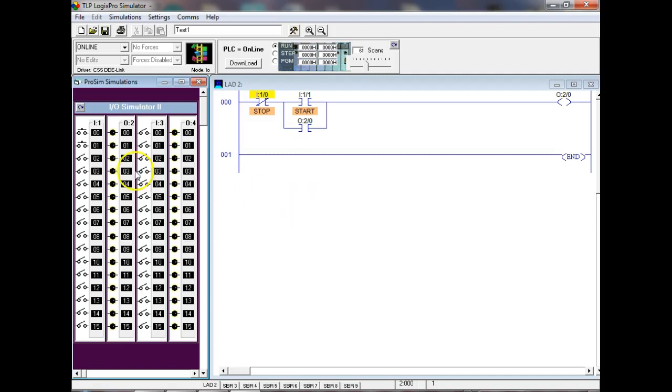So what would happen if this wire broke coming into my PLC? It says examine if open. An open wire is just like an open push button. So if I use a normally open push button on my PLC and call it a stop button, and the wire opens coming in there, I can't stop my motor. So notice it says I've got normally open and it says it's true, right? You understand? So now I come over and push this button and everything seals in and it appears to work.